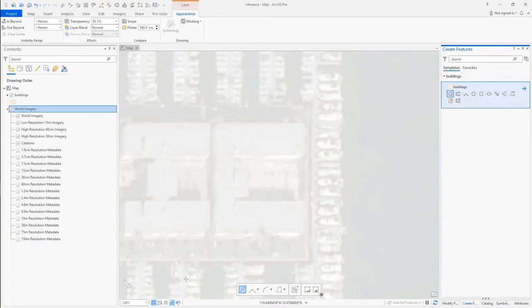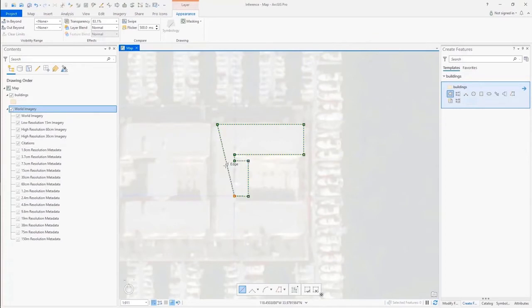Turning on inference constraints from a map's lower status bar analyzes the segment of the active sketch or existing segment over which the pointer is hovering, and displays inferred geometric constraints. When snapping is turned on, the pointer can snap to them using the active snap agents.